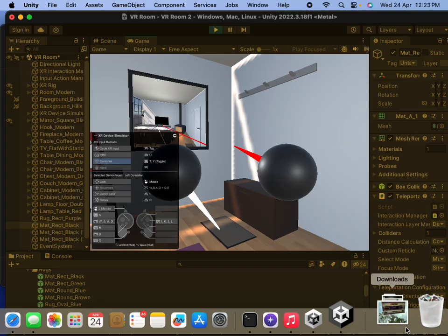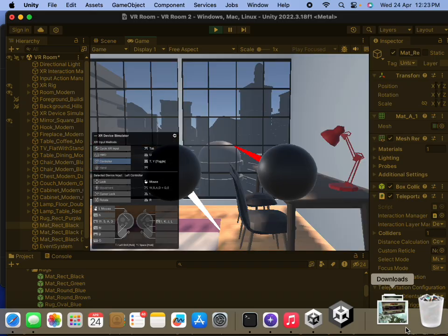Now when I jump there, right now it is facing the corner of the wall. When it jumps, it does not face the corner of the wall, it will face the room, because the rug's local axis is facing the room. Okay, so let me press G. You see, it's facing the room, it's not facing the corner of the wall, right?